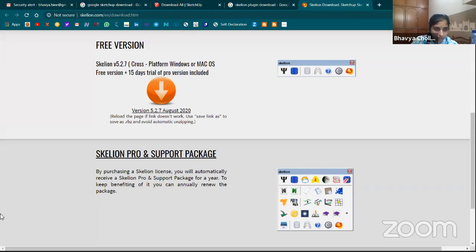Ma'am, solar is completely dependent on climate condition, but the software will show you an exact estimate. Yes, it will also consider the location, Vaishnavi, and to understand the exact climatic conditions, the humidity, turbidity, or wind velocity considerations, all these things are observed in the PVSyst software. SketchUp is only to model and analyze the shadow consideration.